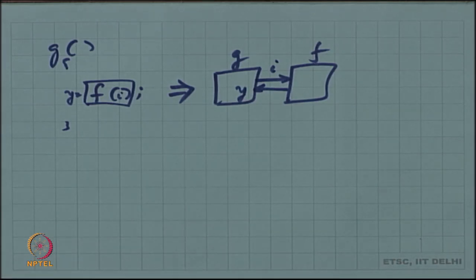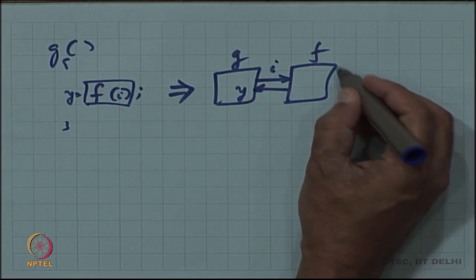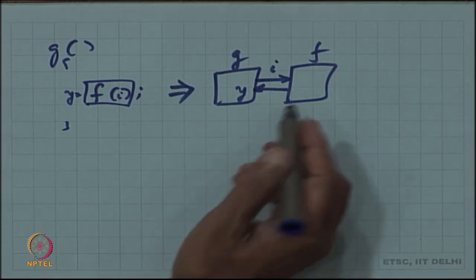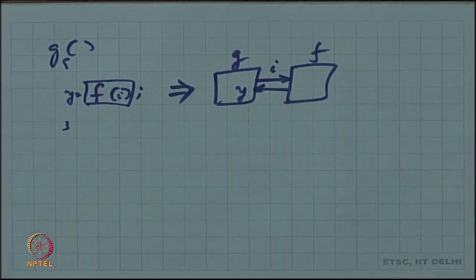of G. You could treat it as this also, particularly if that f is available as a module that someone else designed and you are just instantiating that. That is another way to implement the function. Either way, there would be some benefit from inlining it. That of course has to be weighed by different considerations that are there, but if this is to be separately synthesized, you could say that if this was simple enough, then there is no need to have a separate instantiation of a design, I just make it part of this.